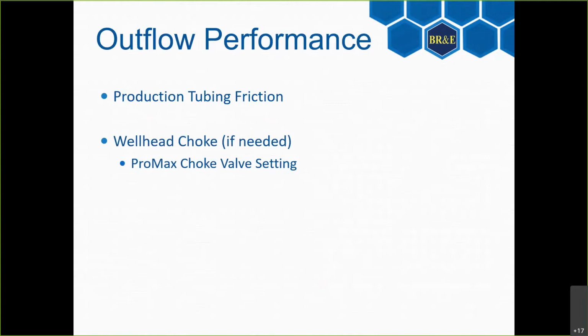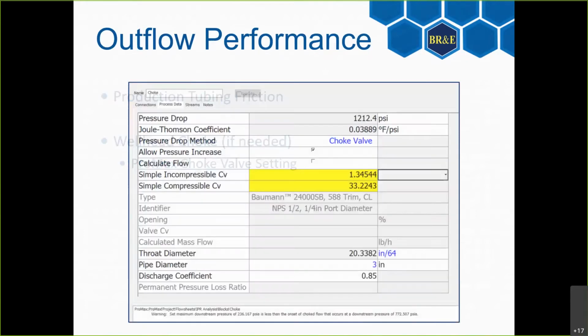But we do have an additional way to model those valves where we can actually set it up as a choke valve and tell ProMax that it is a choke valve, and it will do some added choke flow correlation and equations there. So just to show you real quick, if you're used to seeing valves in ProMax and going into the project viewer to see what those valves are doing, what you'll notice here, the pressure drop is being calculated for us. Anything in black text in ProMax is calculated.